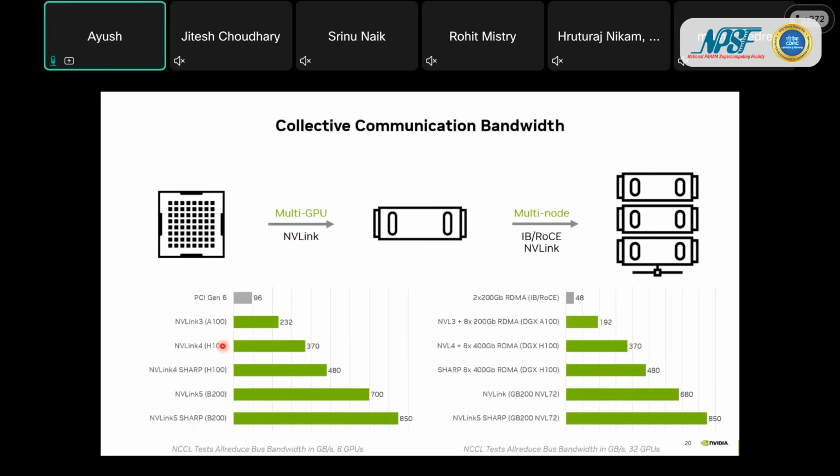Okay, so as I mentioned, we have been discussing NVLink all the time till this point of the presentation. Now for NVLink 3, which is present in A100s, we saw that there are 12 NVLinks from one GPU to the NVSwitch. Each NVLink 3 has an effective bandwidth of 25 GB/s. So 12 of them becomes 12 into 25, which is 300. So there is an effective or theoretical bandwidth of 300 gigabytes per second bidirectional communication for A100 NVLink 3 generation.